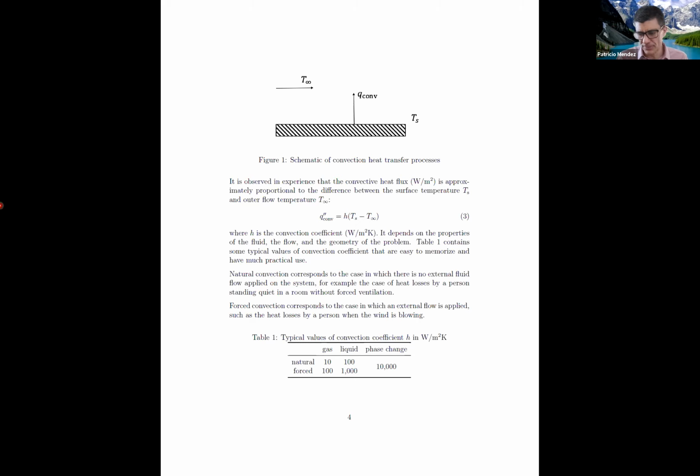We have a different problem. So if we go back now to our notes, a typical value for the convection coefficient for natural convection is more or less 10 watts per meter squared Kelvin. We're going to learn how to calculate it properly, but I'm giving you a ballpark value, very ballpark. But so this is quite awesome.